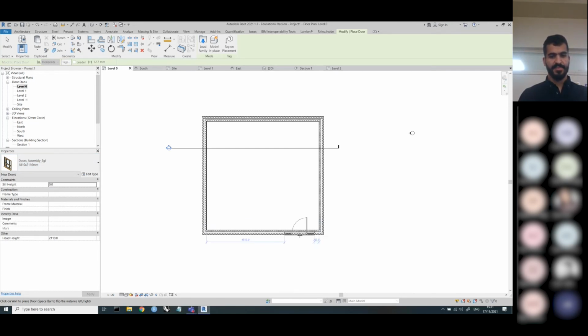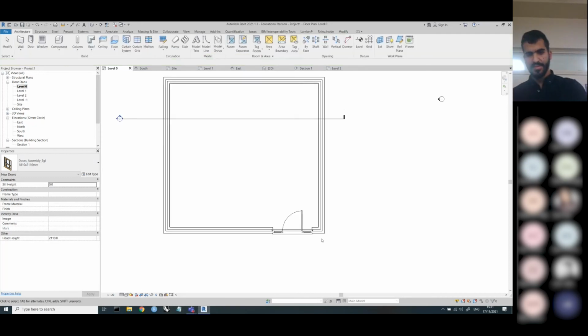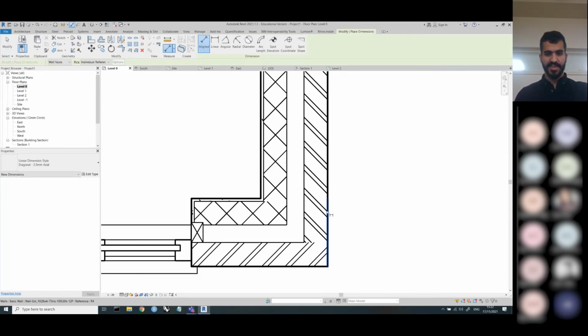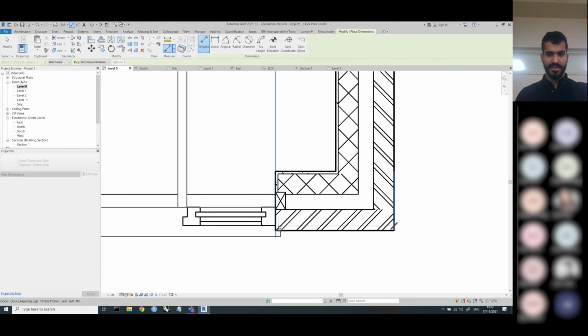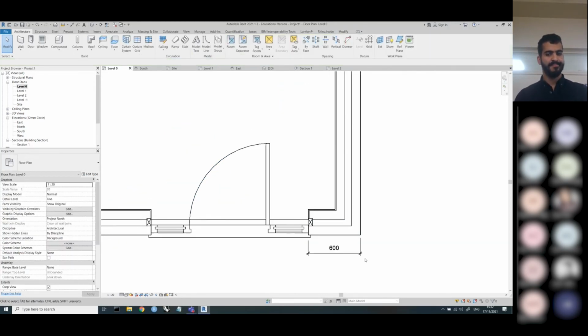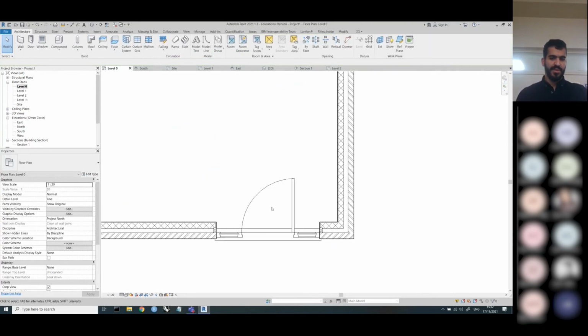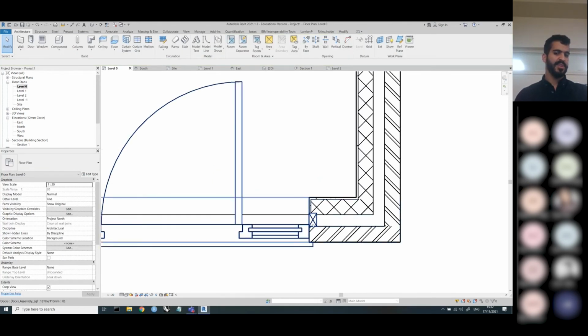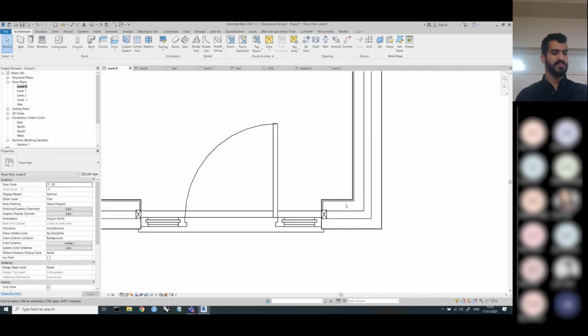So you're going to place it here. Same thing. If I click on the door, I can change this dimension from here. This is if I want to be accurate, right? Here, I can change this to whichever, 600. If it's not opening the right way, I can click on this and I'll switch it. And this family already comes preloaded with some stuff like the insulation stoppers, etc.